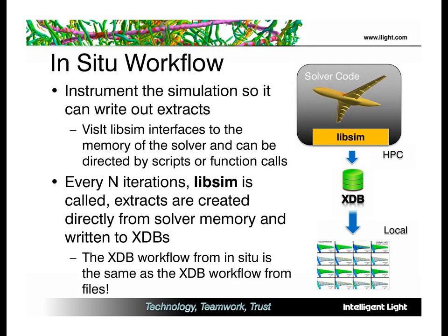In an in situ workflow, you instrument the simulation so that it can write out the extracts directly. So we have a module called LibSim, which you integrate into your solver code, and we share the memory of the solver under the direction of scripts and function calls to create the extracts and write the XDB files. So every n iterations, LibSim is called, extracts are created directly from the solver memory, and written to XDBs.